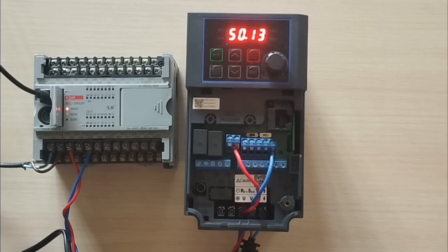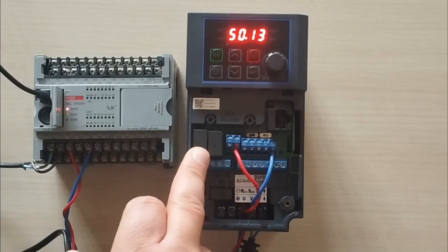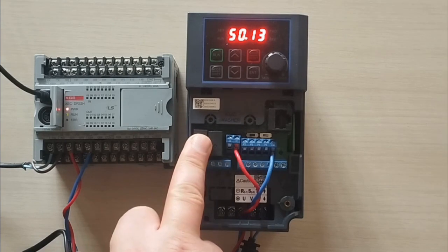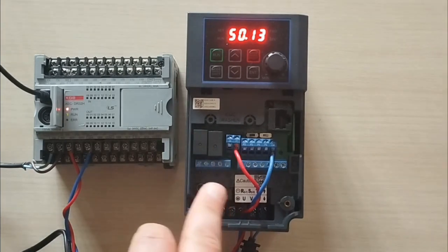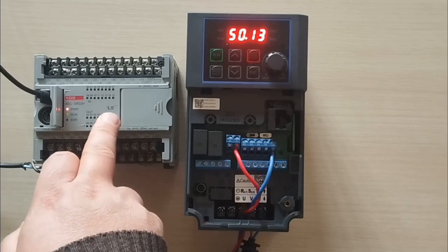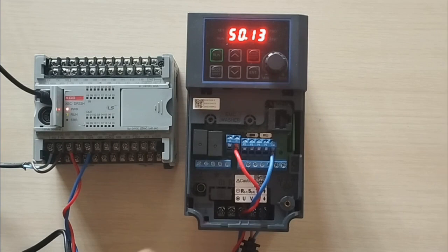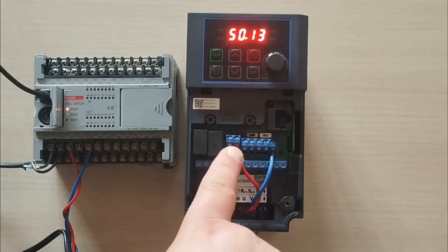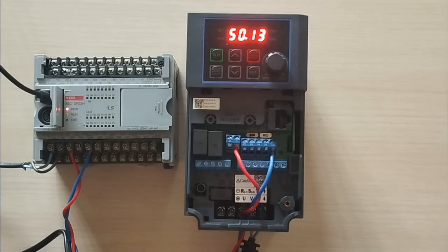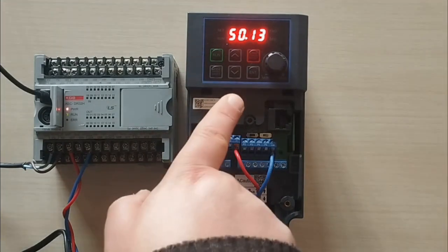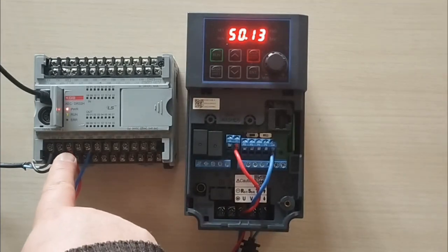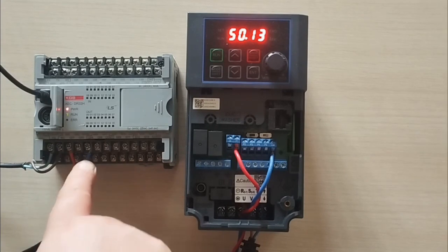Here, as an example, we utilized an LS Industrial Systems G-series frequency inverter and connected it to the LS Electric compact programmable logic controller. We connected its digital input P1 and common CM terminals, which are related to the drive's run and stop commands, to the PLC's transistor output Q0.0 and the common CM terminal. This setup ensures reliable communication between the devices.